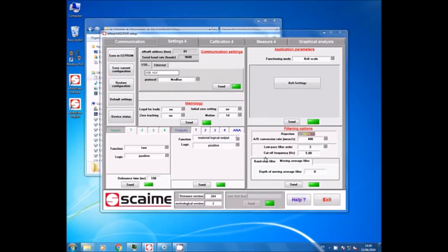Once the calibration has been done, the filters must be adjusted. Here only the frequency 400 measures per second is available. I will use a low-pass filter of order 2 at a cutoff frequency of 1 Hz. I also add a 30 values average filter. If you need help to design filters, see the fast acquisition tutorial and the associated filtering tutorial.